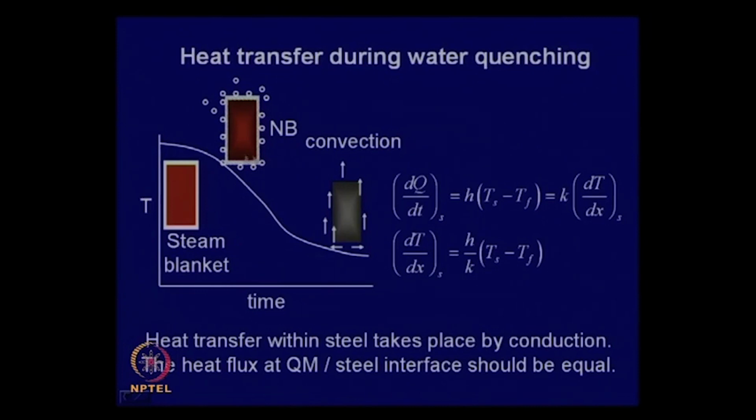Now, the point that comes up here is that the purpose of cooling is, so you have to organize it. The rate at which you are able to extract heat from the surface, by convection, or nucleate boiling or whatever is the mechanism, must balance the rate at which heat flows from the center of the job to the surface. And therefore, it is possible to apply this concept of heat transfer to derive some very simple relationships.